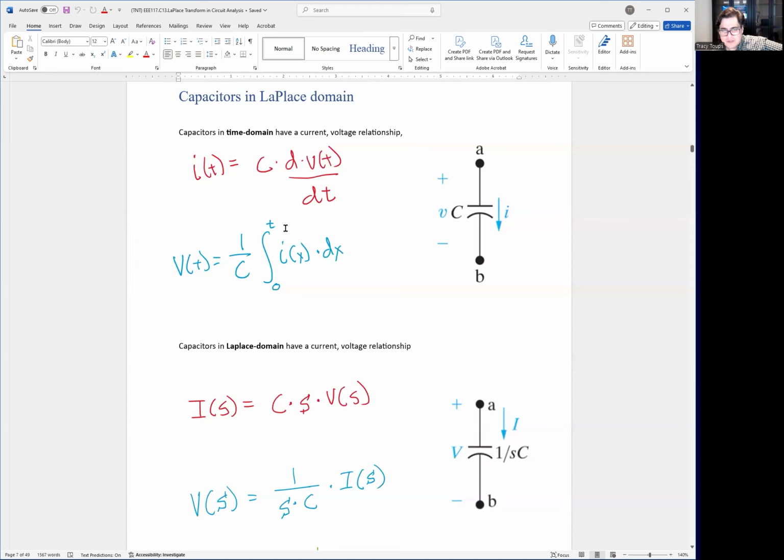Now let's step back real quick. Physically, what does this mean? If we have a preset voltage on the capacitor and I try to add more, I want to force more voltage in. So let's say this voltage is 5 volts, I want to make it 10 volts, right? The capacitor has a lot of room for electrons. So to raise the capacitor to 10 volts, we're going to dump a lot of current to fill up all the room, all the plate with electrons. So that big old cookie sheet, we're going to have to dump thousands and thousands or millions and millions of electrons to fill up that cookie sheet.